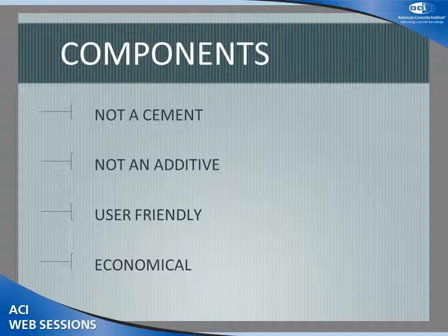In practice, components have replaced cements as the method to produce shrinkage compensating concrete. The previous issues of ACI 223 focused on Type K cements to produce shrinkage compensating concrete. Type K concrete produces its expansion via the production of ettringite crystals in the concrete. Type G concrete produces that expansion with the production of calcium hydroxide platelets in the concrete.